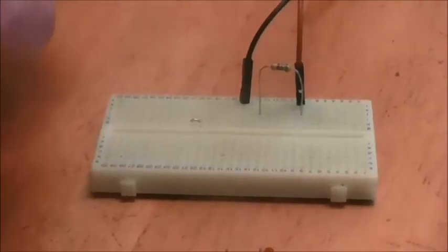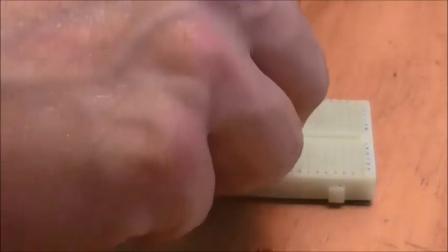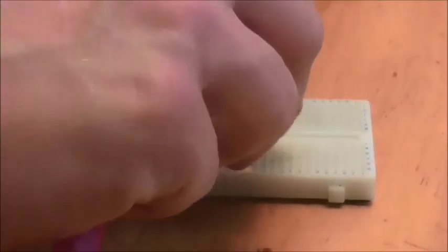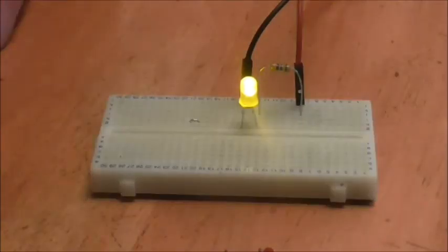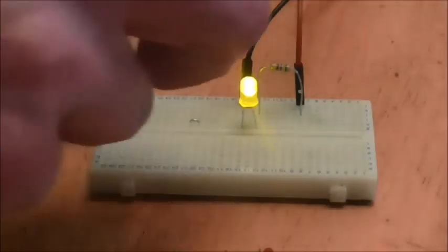Let's change the colour. And we're going for yellow. Now, this also uses gallium, arsenic and phosphorus, but it mixes the ratios around a bit. And by mixing the ratios around a bit, you'll get a gradual shift from 700 nanometers or so down to around 600. Let's change the colour.